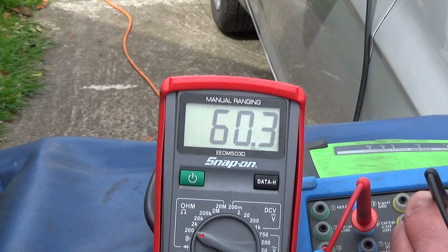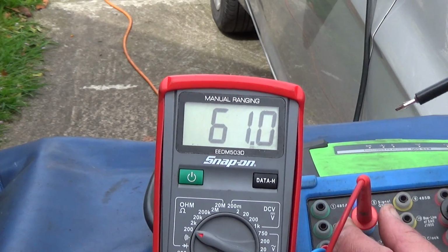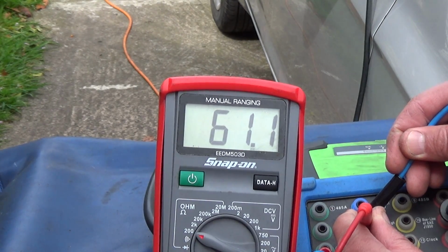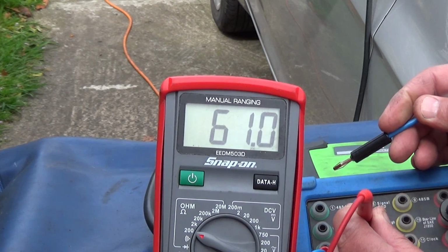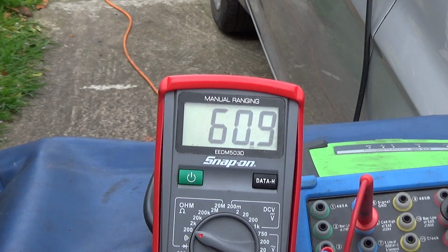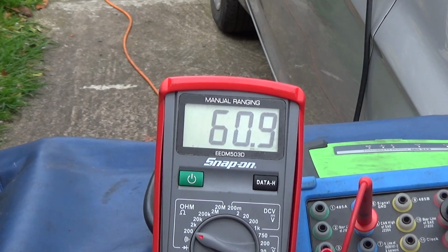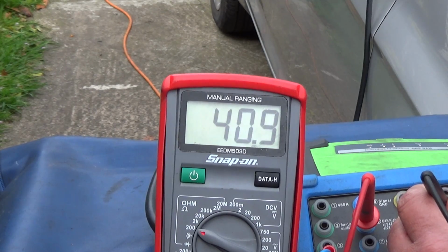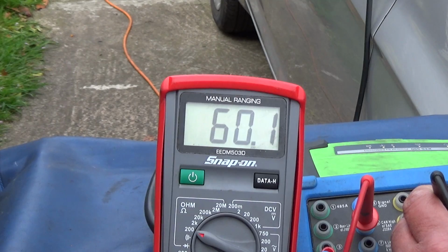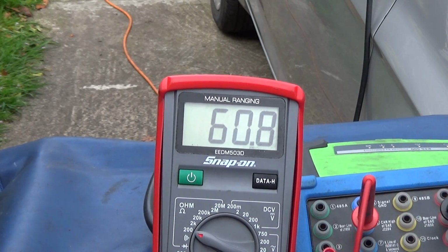And see how the resistance doesn't change? And then on the high speed, the same thing. The resistance doesn't change. Okay. But what that tells us is that when we've got 2 120 ohm resistors in parallel, our physical network is complete. And a short to ground will make absolutely no difference to the resistance in the circuit. Okay. Now,